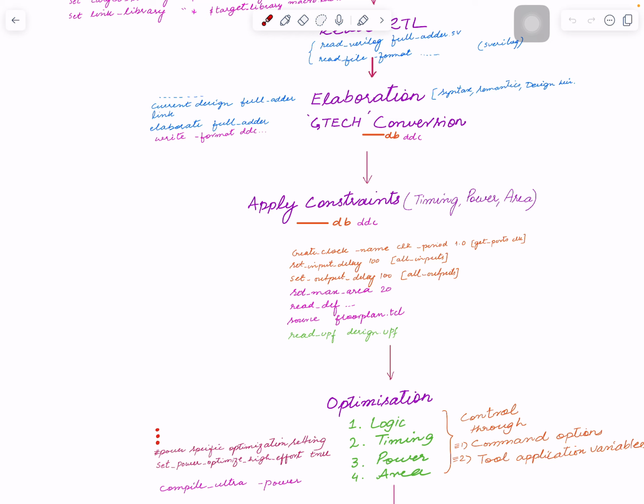Your starting point, a gate level netlist, is a starting point for your physical design implementation. And if your starting point is good, the following stages will do even better. And if your starting point is a low quality netlist, then your following stages need to do a lot of work, and you will see a bigger miscorrelation between your QoR reports in the later part of the design to earlier part of design.